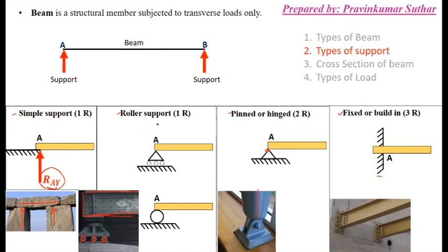If I'm talking about the roller support, it is the same: it will also support only vertical force, vertical load, but a little bit of sliding is allowed. As you can see, these are the rollers. So if it is required to slide the support, then the roller support can be used, and a limited sliding is allowed.